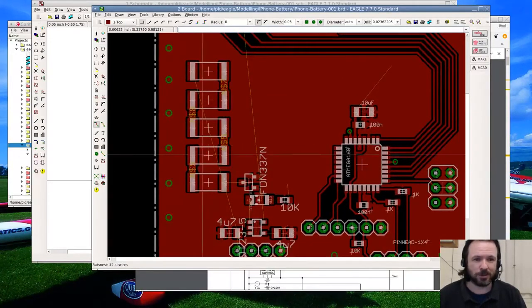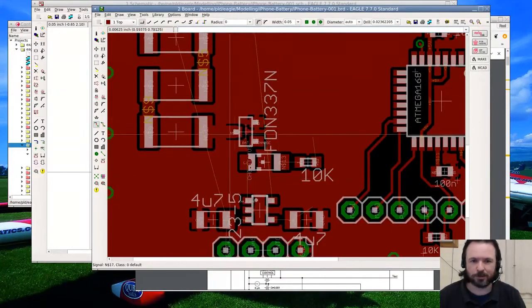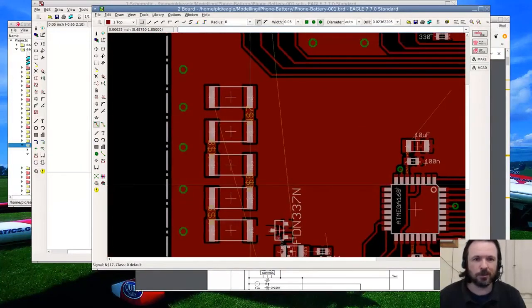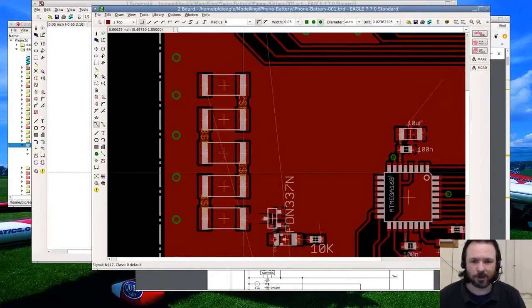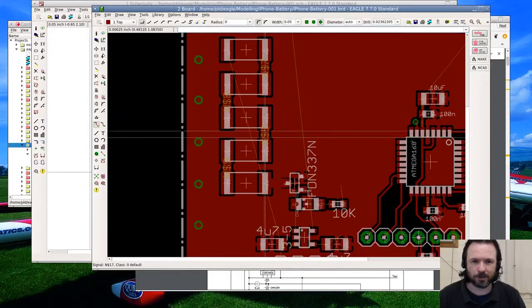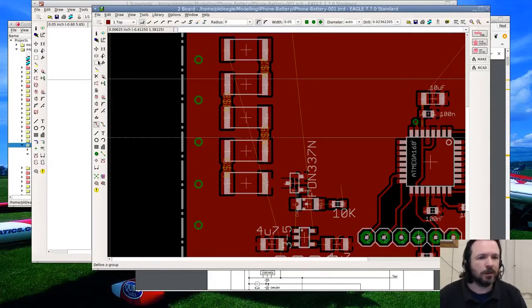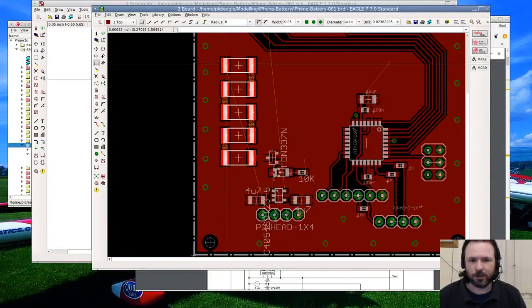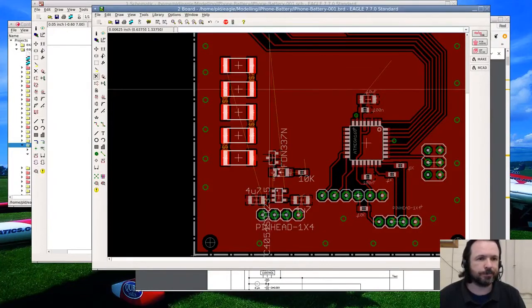In the meantime, I need to start etching this out. Etching it out? No, drawing it out. Yeah, let's use a 50mm trace on a pad that barely can handle that. Why not? And okay, it's upside down. By upside down, I mean I really probably should have had it so that this resistor here is closest down to here. That's a bit stupid of me. Let's rip it up.